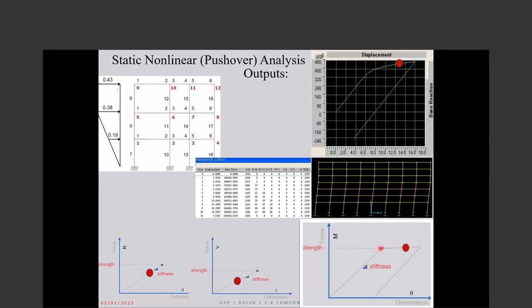But the stiffness of this element is not this much anymore, it is 0. So the contribution of the stiffness of this element to the building stiffness is gone. So the building stiffness reduces. And little by little, the building stiffness reduces because more and more deformation control elements get damaged till it comes to this point. And then the software can also give us some